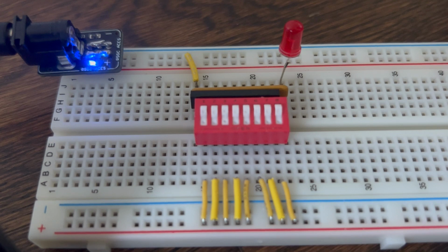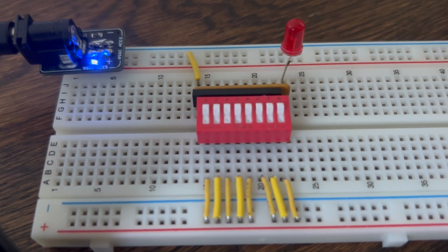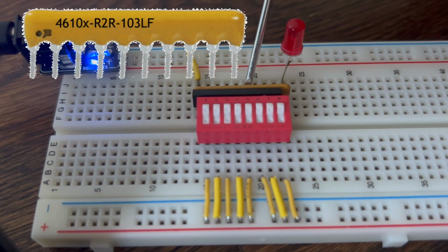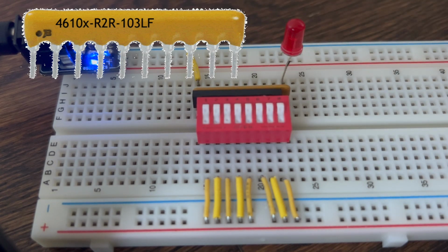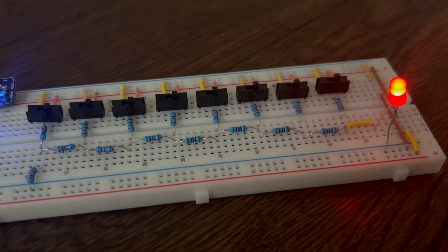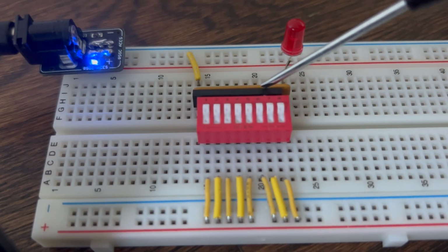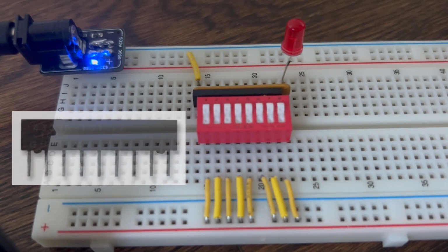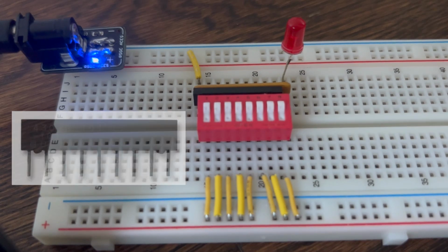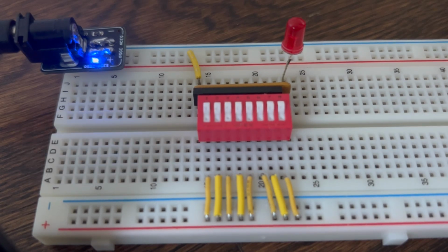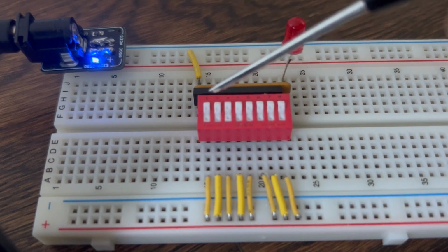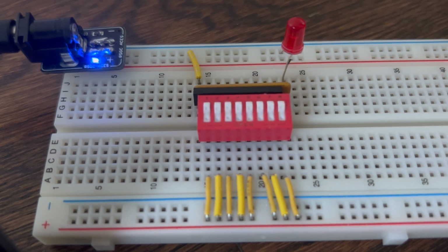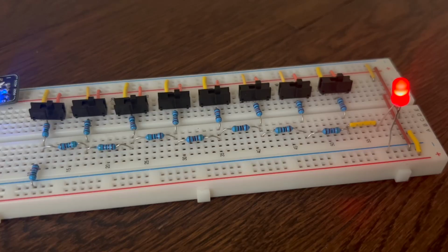This is the R/2R ladder, but more compact. This here is the resistor configuration of the original circuit, and all the resistors do the same thing, but just compressed into a chip. And this is a network of resistors grounding the leads to make sure the voltage isn't floating, which is when a signal isn't connected in any way to the building ground system, but rather has an isolated ground reference point. These are the switches, and they're just more compact to make it look neater, and it basically does the same thing as our 8-bit.